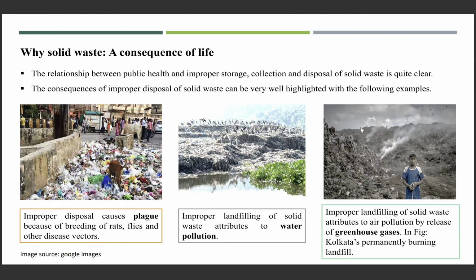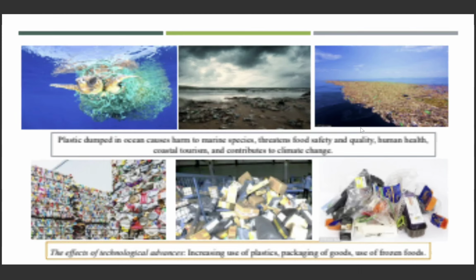Also, during summer we have all heard news of fires in landfills. This is because degradation is taking place in the biodegradable matter of the solid waste dumped in the landfills. If anaerobic biodegradation is taking place, then methane is generated, and methane catches fire very easily. In summertime, since the temperature is very high, they catch fire, and there are a lot of cases of fires in landfills in our country.